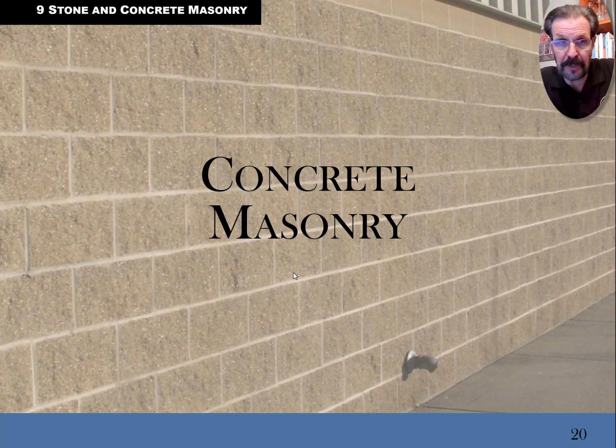Anyways, this particular picture, before I left this page, I wanted to point out that these blocks are not the plain vanilla boring masonry blocks. These are what we call split face blocks. They actually make them double wide: two blocks twice as wide as the block they want, and they have a big wedge and they break it in half. They literally split it like an axe, a very heavy duty axe on a hydraulic system that breaks that block into two pieces. And so you get this irregular shape that makes it look a little bit like rock.